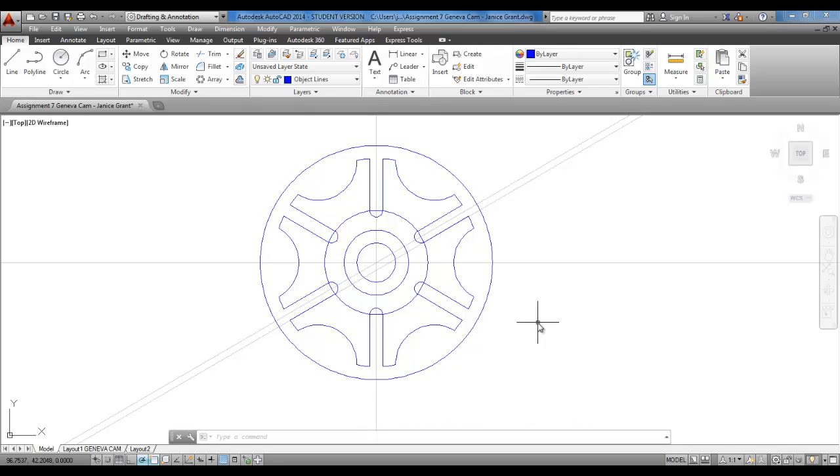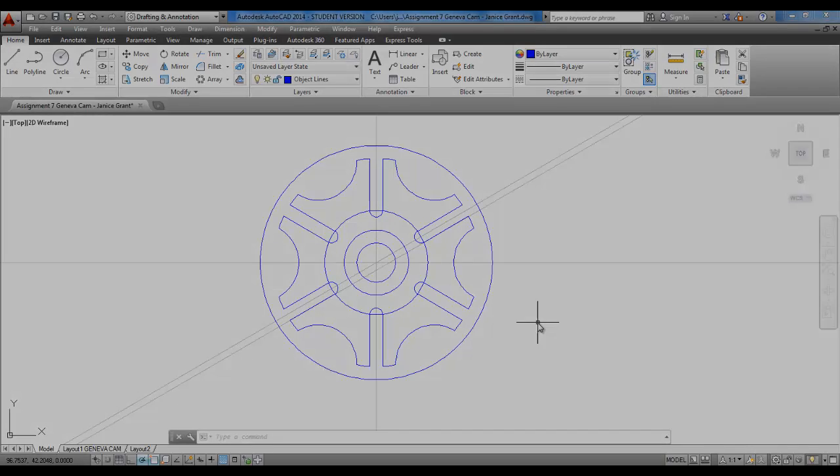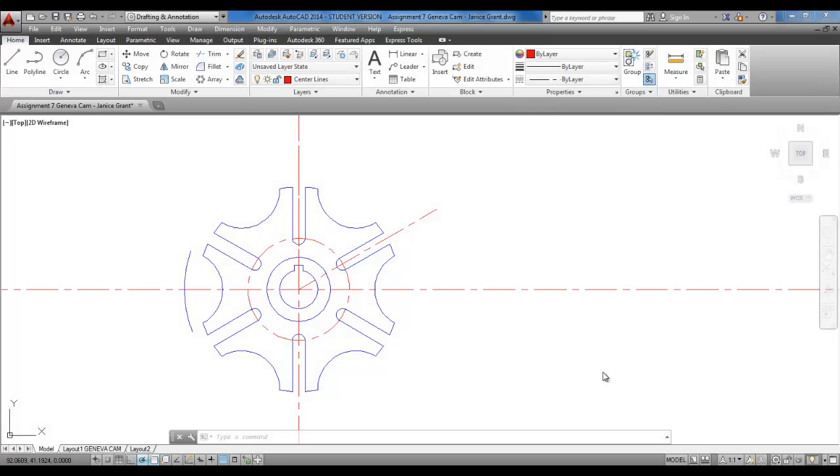So continue with the drawing until you've finished the worksheet or the image that I'll show you shortly, because I'm going to pause it and go ahead and work on it. When you're using angular dimension for these 2 lines, it won't select a construction line. Now, in the past, construction lines were just regular lines. But here in 2014, when I use angular dimensions, it won't let you select a construction line.